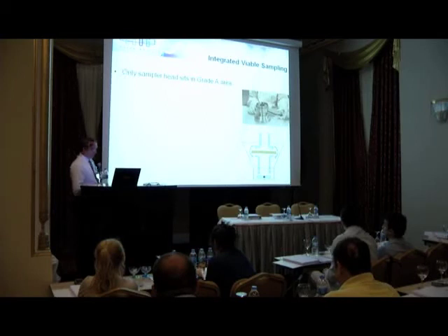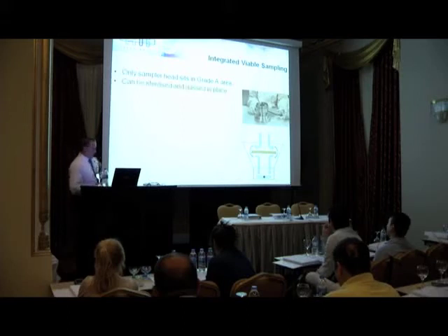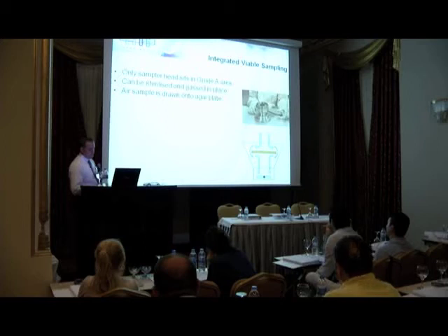With our solution for viable monitoring, the only device that sits inside the isolator or filling machine is this head here. It has an integrated impeller, it can be gassed, cleaned with alcohol, but everything else sits outside of the isolator, because obviously if you've got too much equipment in there, you've got no room to process. These devices can be sterilised and gassed in place, as I previously said. Air sample is drawn onto an agar plate. The impeller is underneath.